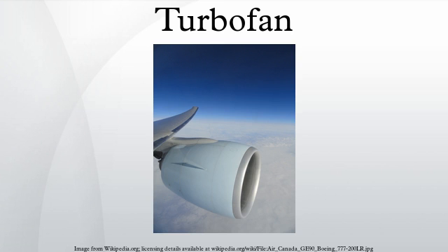Another name sometimes used is ducted fan, though that term is also used for propellers and fans used in vertical flight applications. The difference between a turbofan and a propeller, besides direct thrust, is that the intake duct of the former slows the air before it arrives at the fan face. As both propeller and fan blades must operate at subsonic inlet velocities to be efficient, ducted fans allow efficient operation at higher vehicle speeds. Some large modern turbofans, like the Trent, have blade tip speeds of 1,730 km/h.